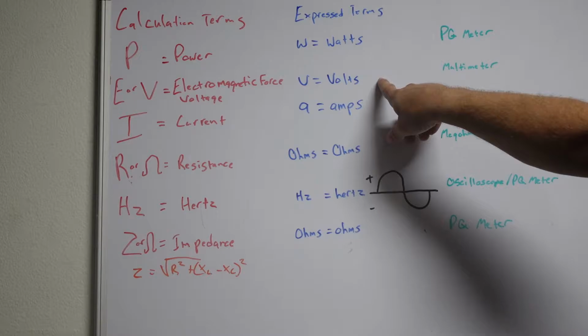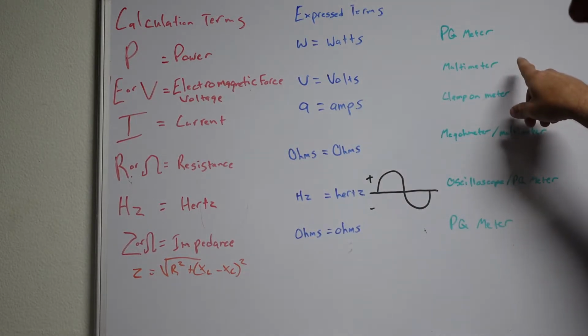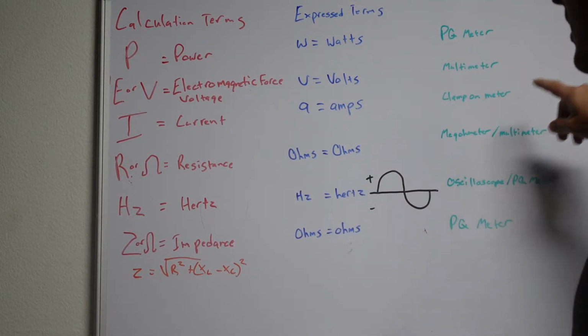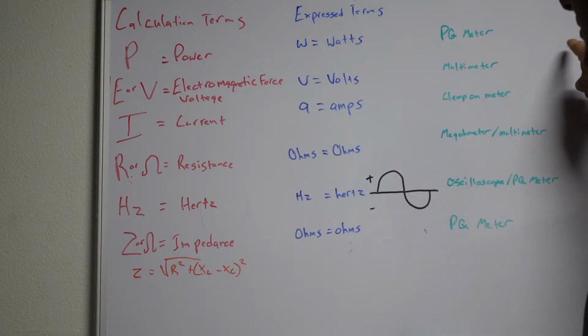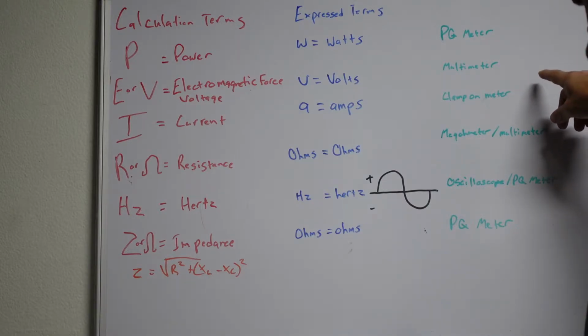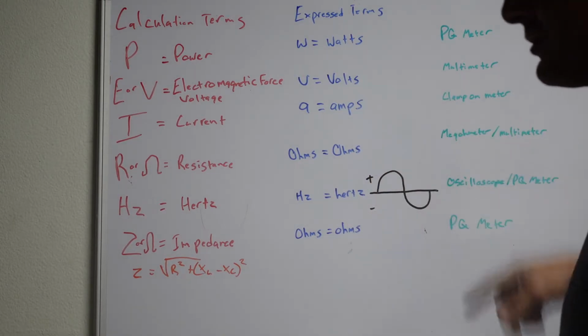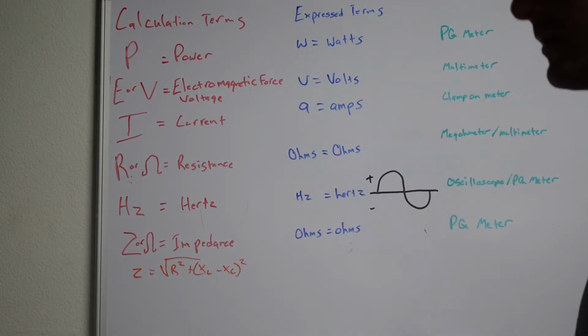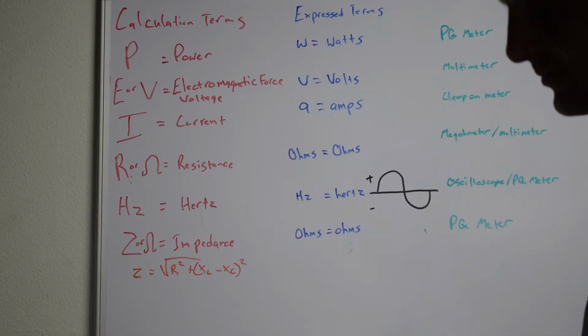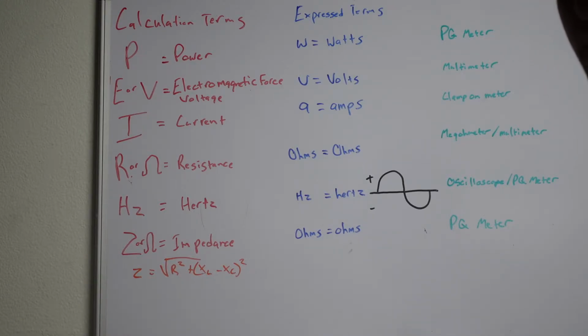You can also get that typically with a multimeter, like I said before. For volts, I'll just use a multimeter. There are voltmeters that will work for that as well, but a good multimeter will do that. Amps, I usually do with a clamp-on meter, which, in my case, is a Klein one that does that.